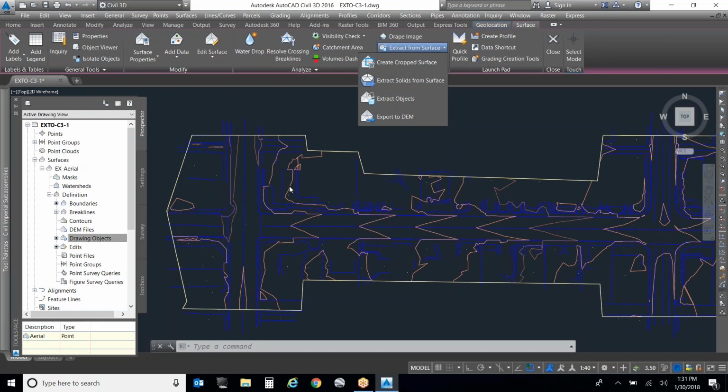True, you wouldn't. So there's a couple different approaches to that. You could add the points, but when you do that, if your survey is different from your topography, you're just going to see this huge spike out of nowhere, right? So adding those points to this surface, you'll get a mountain like this that shows up. It isn't a very good solution because it's going to affect anything. The last triangle could be, let's say, 15 feet away. Yeah. So over that last 15 feet, you're going to get this mountain, right?